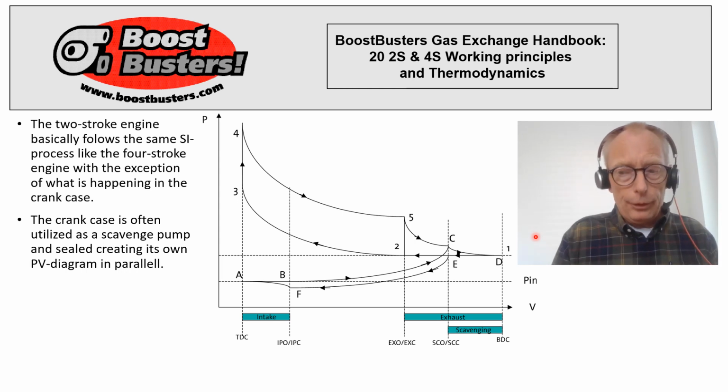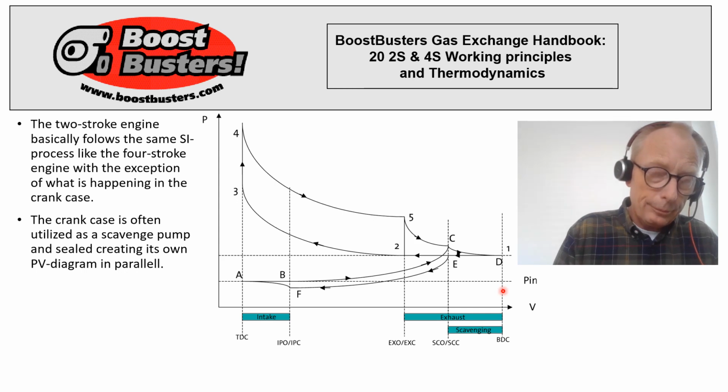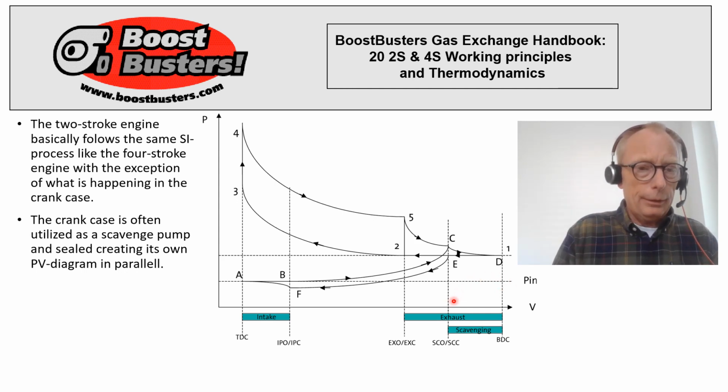The second difference is what's happening in the sealed crankcase, which acts as a pump. So we also have a PV diagram happening in the crankcase.